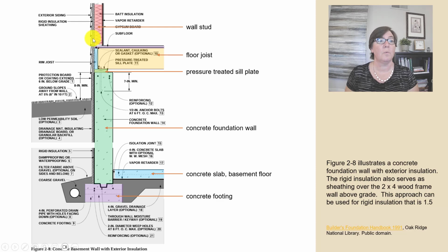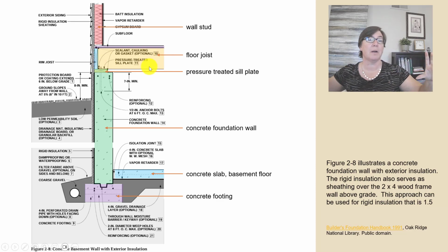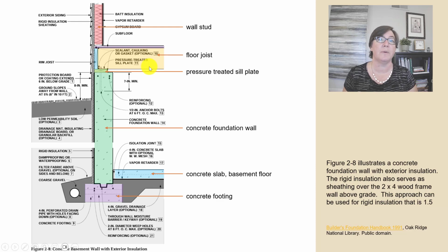All right. Your wall is built up here. Here's the wall stud of that exterior wall system with the plywood subfloor. This is where someone would stand. Right. Here is the floor platform, which we'll be studying more next week, right? With an edge joist or rim joist. Got a couple of different names over here. And this is going to be the floor joist. It's going perpendicular to our frame of view in this picture.